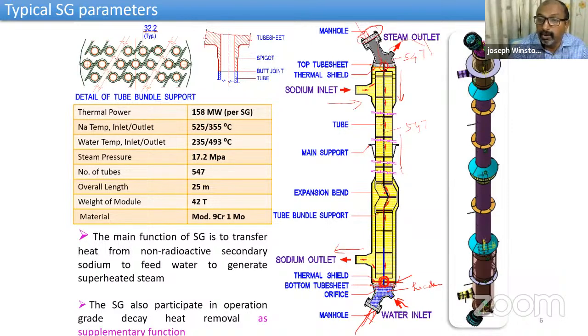So through the tiny hole, we have to push the cable all the way down to the bottommost point to inspect this also, while it is doing the inspection along the tube, full length of the tube. So in case of any kind of abnormal signals coming out of eddy current, normally eddy current systems are used. And this is a ferromagnetic material, so it has to be a remote field eddy current technique.